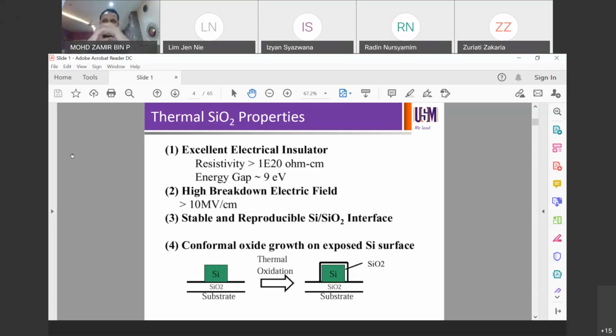But on the other hand, if you are looking at that particular measurement, there's always two things that you have to think about. One is the uniformity. So that means you want to measure as many as possible, but you also have to bear in mind that you have WPH, wafer per hour capacity, or throughput that you have to deliver. So that means if you measure more points, you're going to slow the process down. And if you measure less point, you don't see much in terms of uniformity.